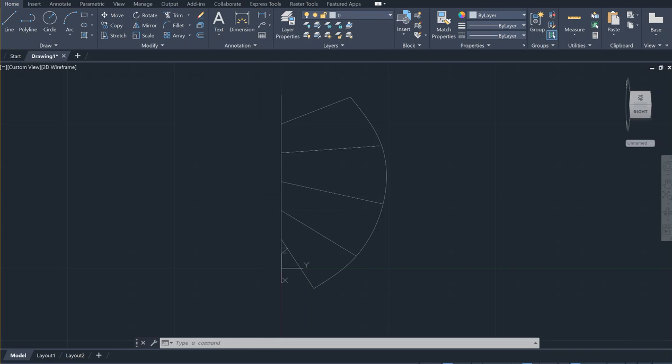Either will work. And we left at this point last class, and I'm going to demonstrate how to create a profile for the turbine blade, and then we're going to simply generate a profile, draw the profile, and make the extrusion or loft command. Either one of them will work for us.